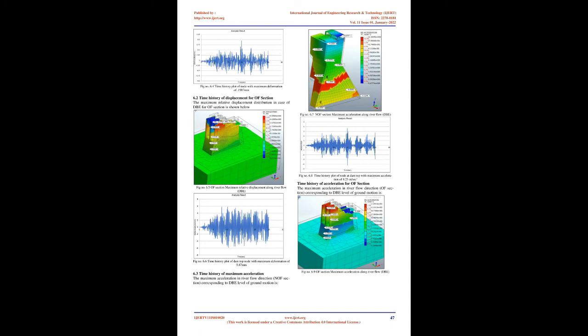Time history analysis. Concrete hydraulic structures behave in a less ductile manner during earthquake as compared to RCC building. Such behavior combined with complicated structure foundation and structure water interaction requires time history analysis. Linear time history analysis calculates the solution to the dynamic equilibrium equation for the structural behavior, displacement, element force etc., at an arbitrary time using the dynamic properties of the structure and applied loading when a dynamic load is applied.